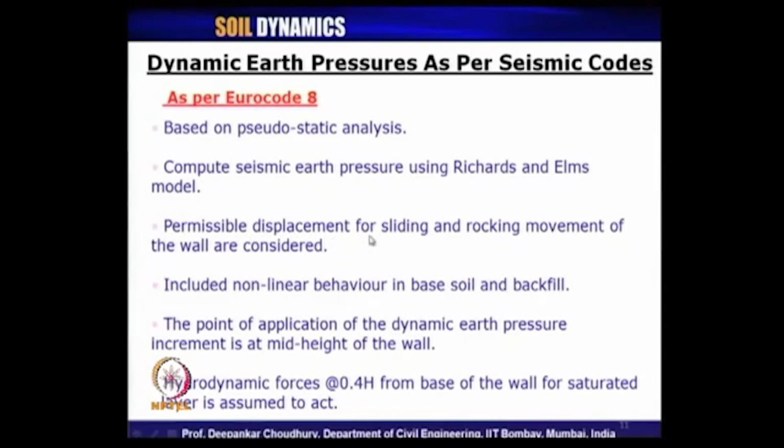So, permissible displacement for sliding as well as rocking movement of the wall have been considered in this, and it includes the nonlinear behavior of the soil and backfill also. Which is another advancement. And the point of application of dynamic earth pressure is still considered at mid height, and different hydrodynamic force, if it is a saturated layer, is mentioned in this code.